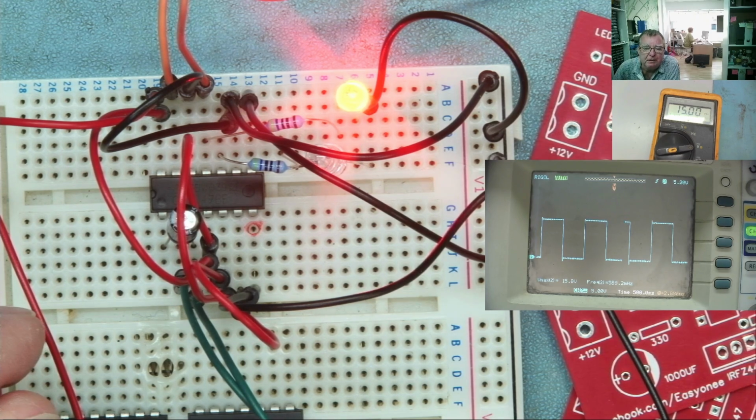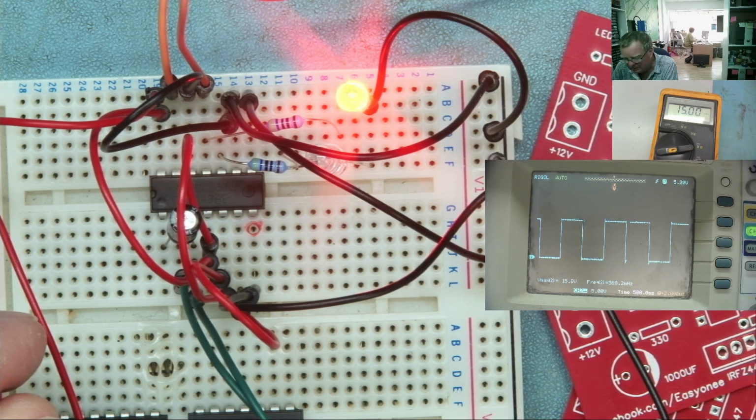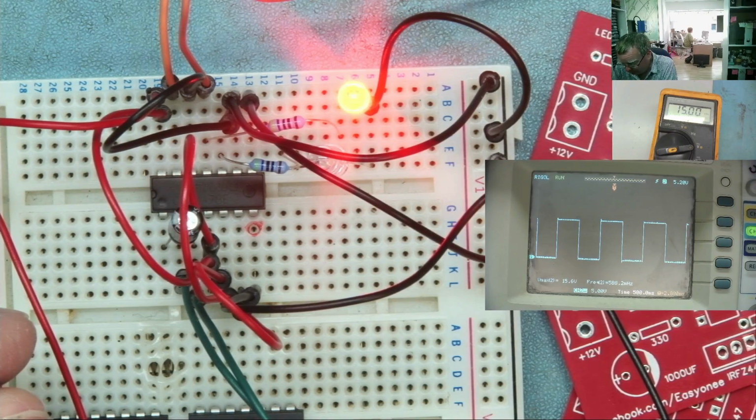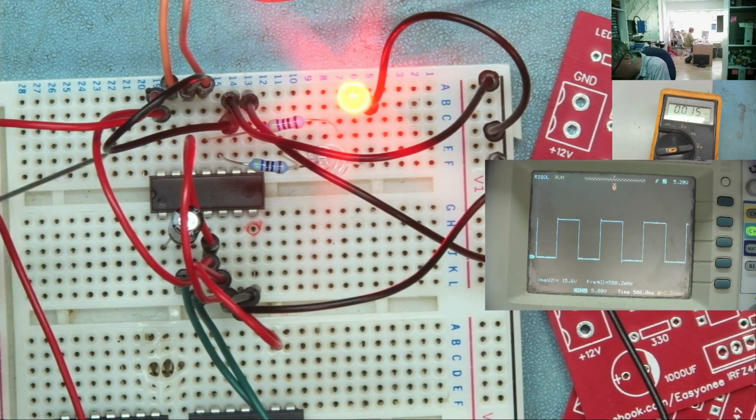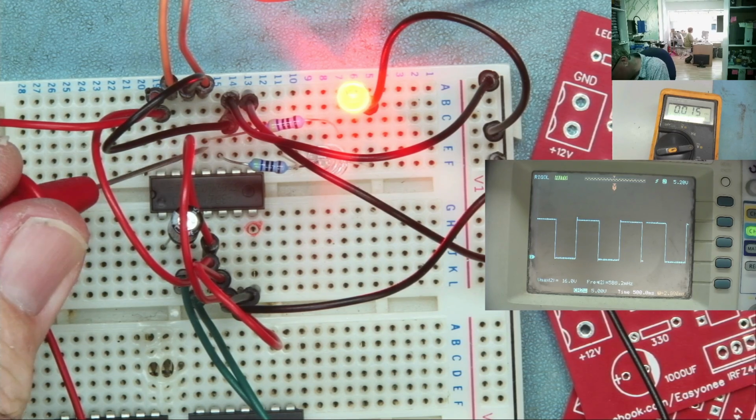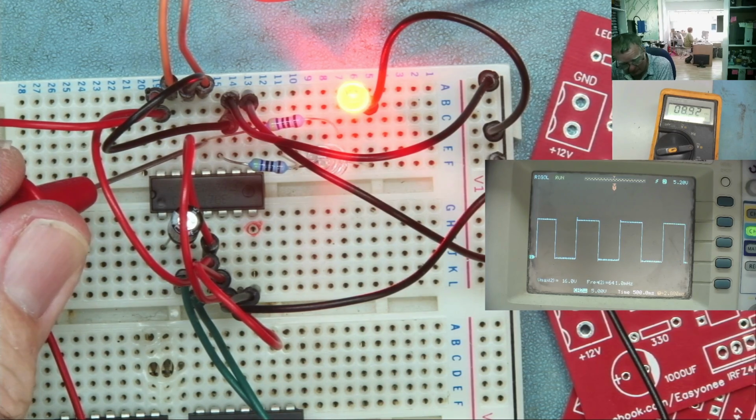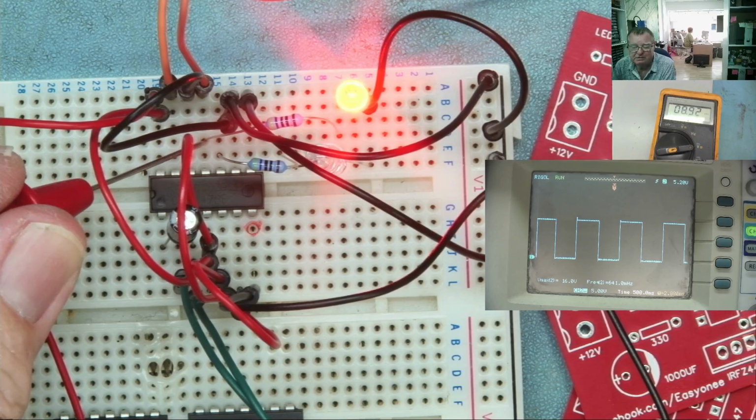I think it says 15.8 actually, but 15.6 maybe is not totally accurate. And I also think that little spike on the end of the rising and falling edge is probably my 10 times probe, which just needs adjusting slightly. But yeah, 15 volts. So we know again pin 13 is going between supply and ground, and the LED now will have almost 9, so we get about 60%.